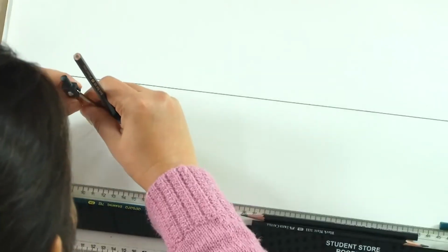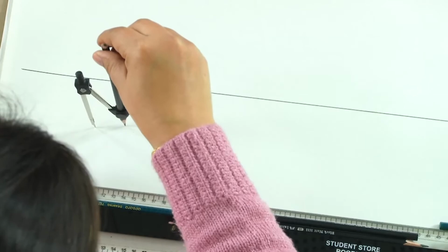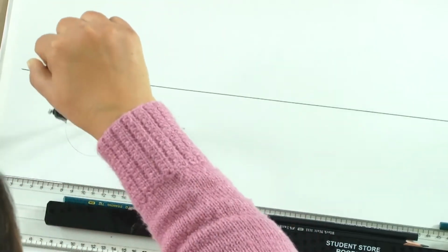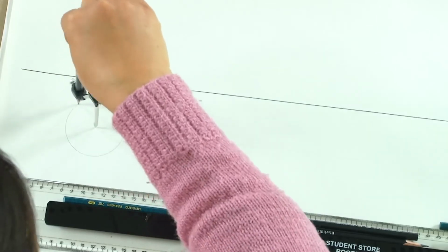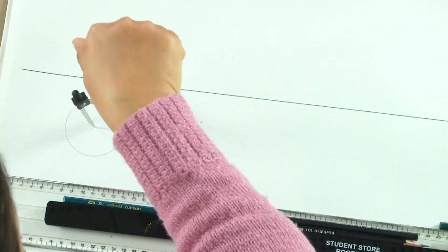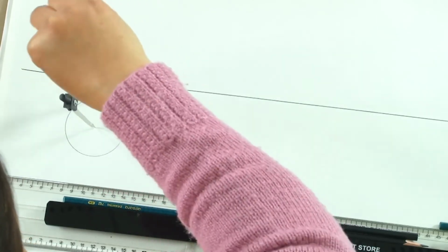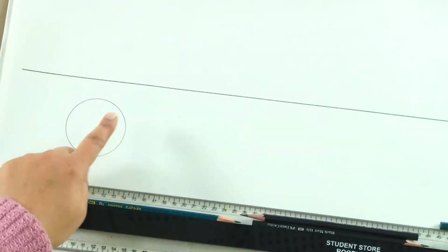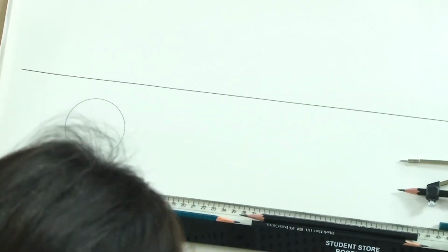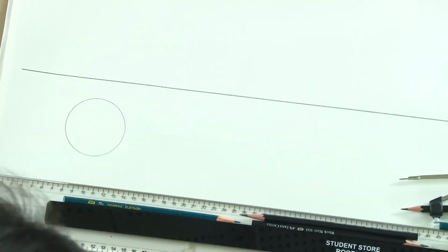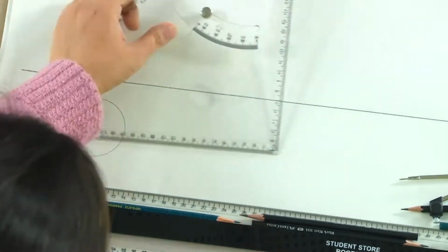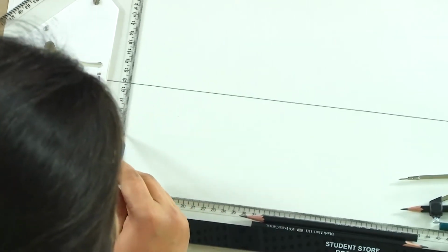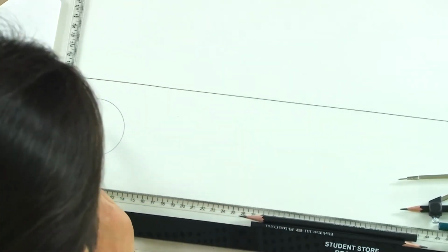and keeping the center of the circle on this line, we will draw the initial position, assuming that the circle was parallel to HP and perpendicular to VP. So we will draw its projections. Now this that we are drawing, which is the initial position that we have assumed, we will draw lighter. It will not be drawn very dark. Then we take its projections.